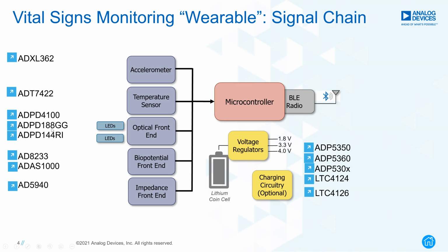to get you the right optical processing for your application. Another area is biopotential front end measurement, where we have parts like the AD8233, which is a very low noise, low power AFE. Again, the power consumption for this device is around 45 to 50 microamperes, delivering a common mode rejection ratio of close to 80 dB at 60 hertz with a 50 microampere supply current, which is a very important and useful factor for these kinds of applications.